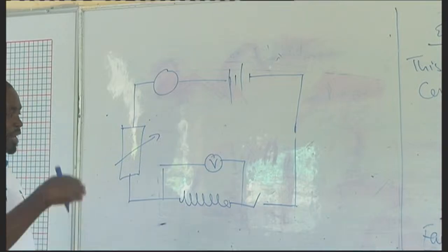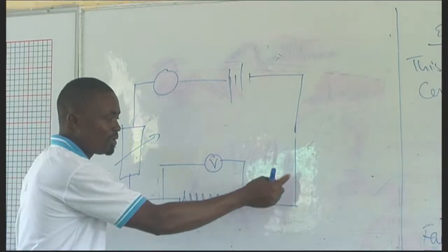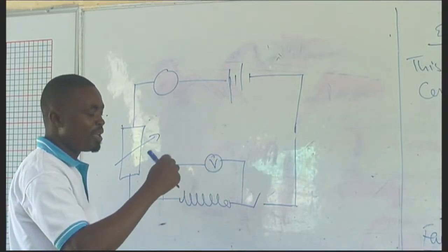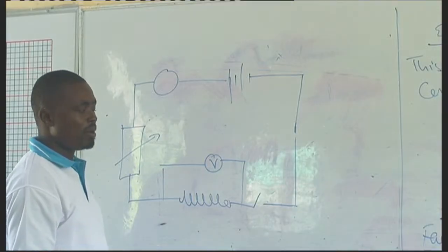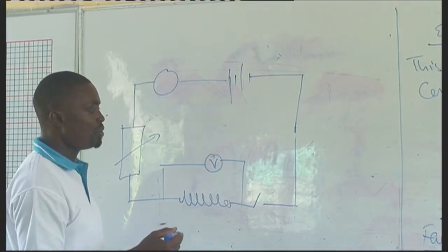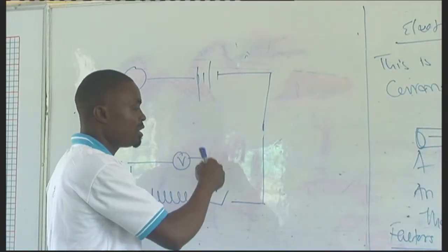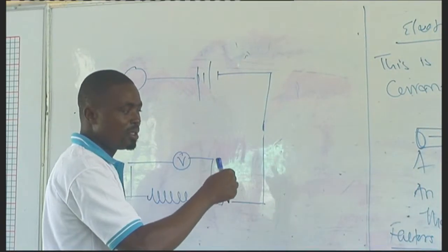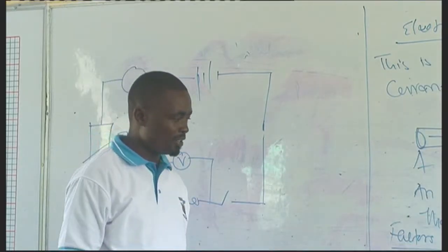When temperature is raised, the atoms of these metals will start vibrating. When atoms vibrate, there will be collision between the atoms and the electrons as the electrons are moving. And that collision interferes with the movement and therefore enhances resistance.